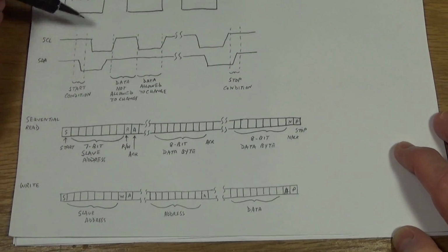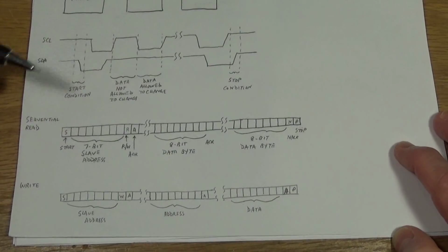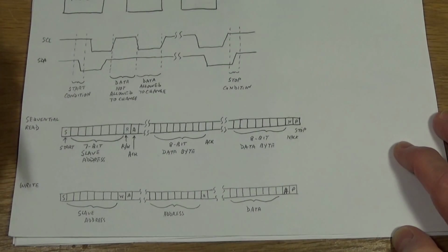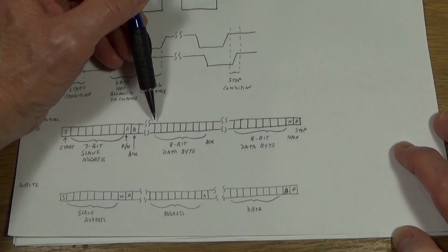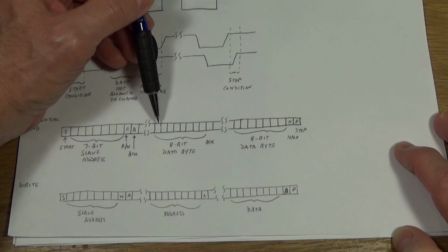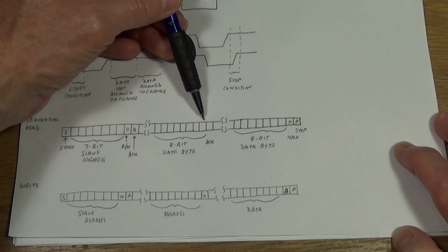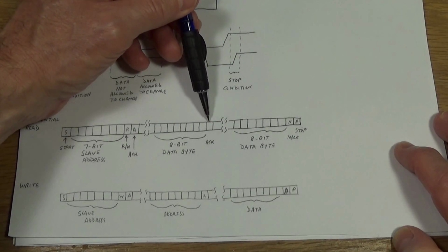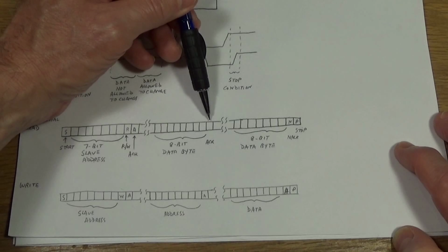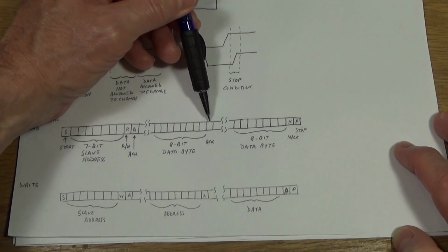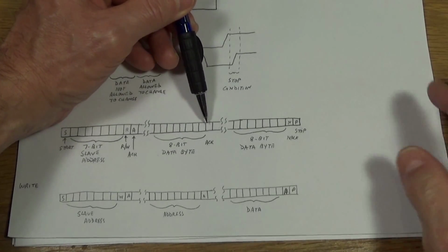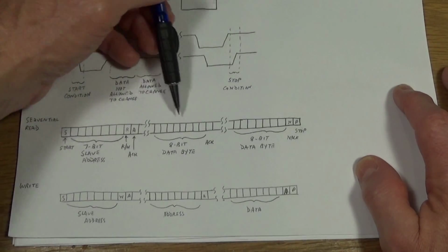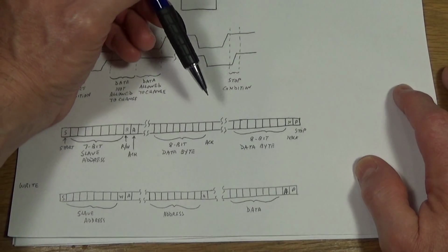of data. And by the way, the data communication on the bus is a byte at a time, 8 bits at a time. So what the slave does is it'll put out its data 8 bits at a time with each clock, and then the master will issue one more clock, and then since the master is receiving the data, it will acknowledge by pulling the acknowledge line low. And this will continue. The master can keep clocking for as long as it needs to get the data that